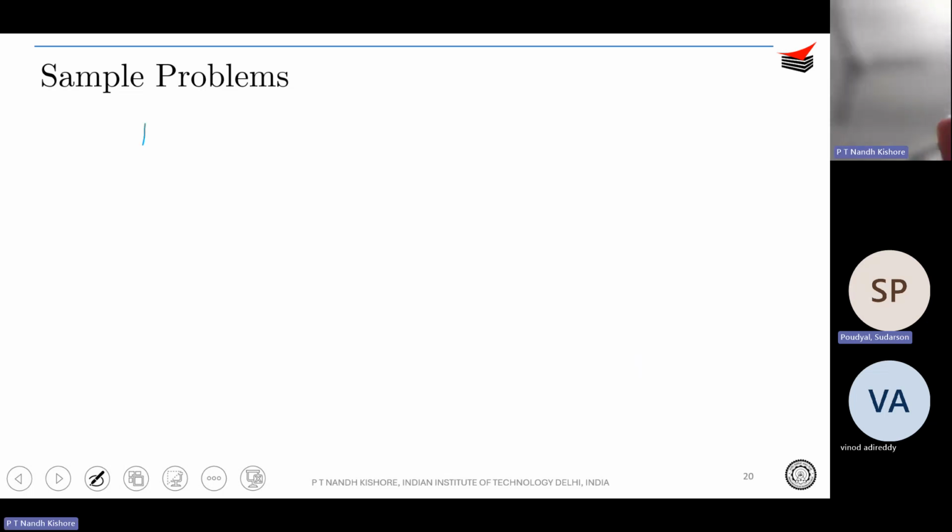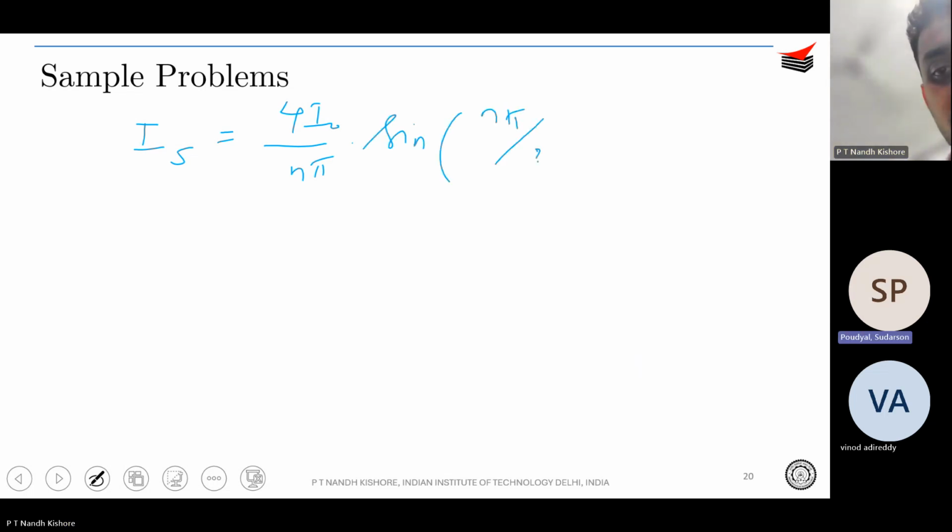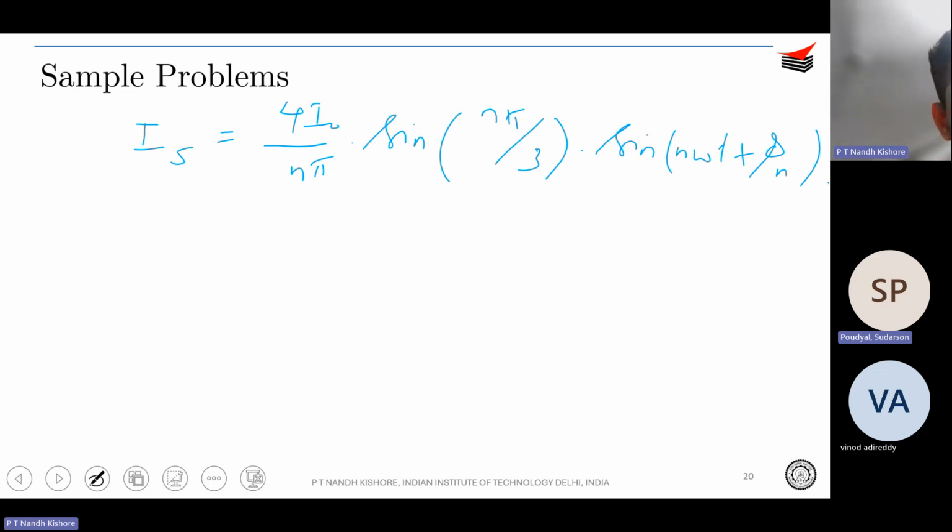Okay. So you have your iS is 4 I naught by n pi sine n pi by 3 sine n omega t plus pi n. Correct?